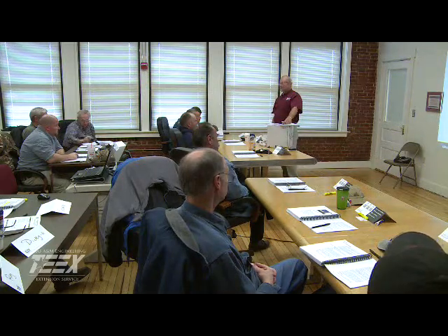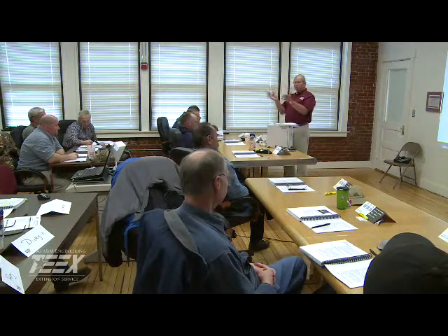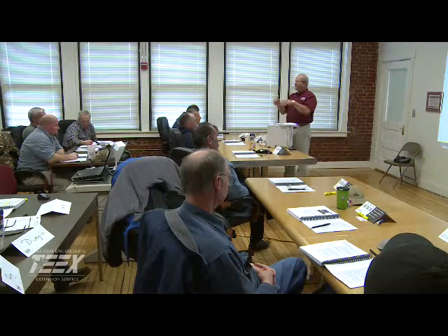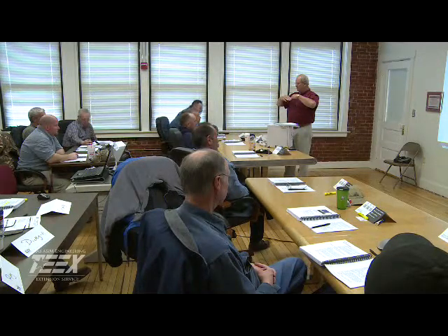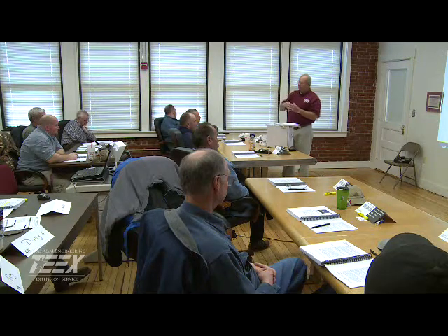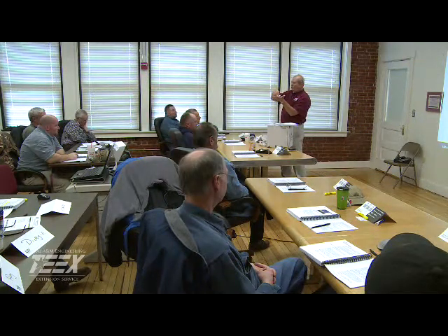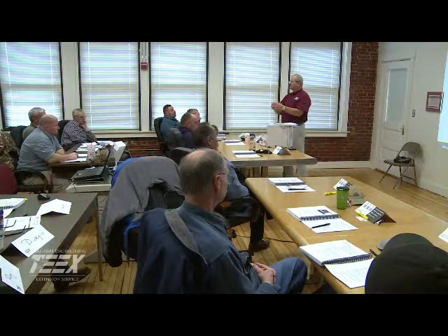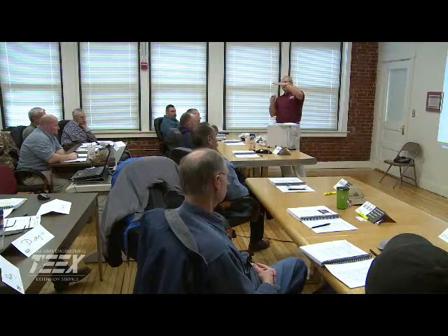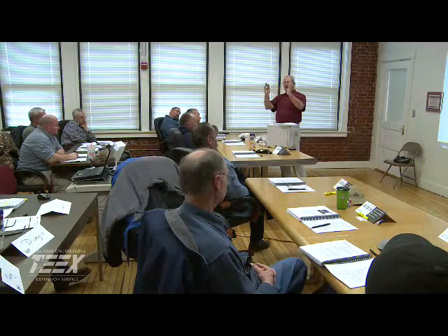And what's gaining popularity again is the resilient seat. You have a plug valve, it's coated with neoprene or rubber, and you have a smooth inside casing. The housing is smooth. There is no seat. And so what happens when you close it, the neoprene squashes down onto the interior of the casing and thusly gives you a complete seal. Double disc has a wedge in it, and as it hits the bottom of the valve, the wedge spreads the two discs out and it sets up against the seat.